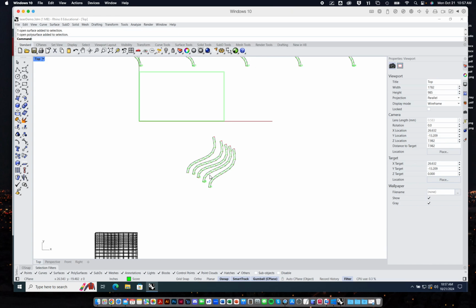Again, we encourage experimentation. That laser cutter, going from bits to atoms, right? It's a strange process, and I think you'll come across this. Some of the things you took for granted in Rhino, when you draw a line or a curve with a certain precision, maybe 3 or 4 decimal points of accuracy, don't hold so much weight when you're trying to build it out of chipboard, right? Or you even buy a sheet of chipboard, you realize the corner's a little bent, and nothing's really perfect in the real world.